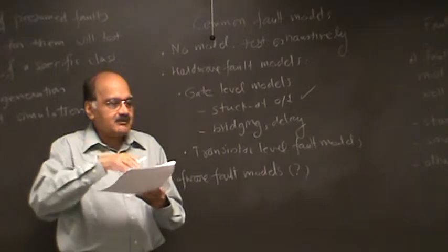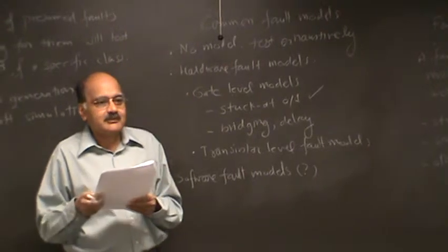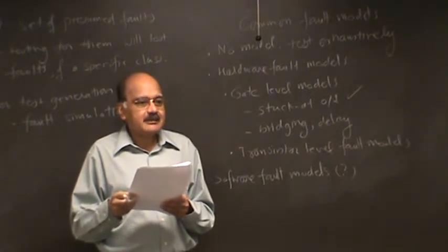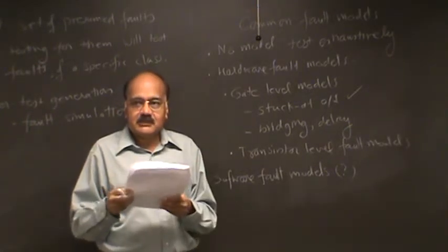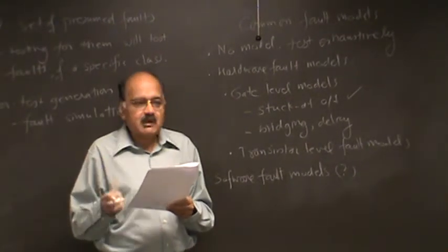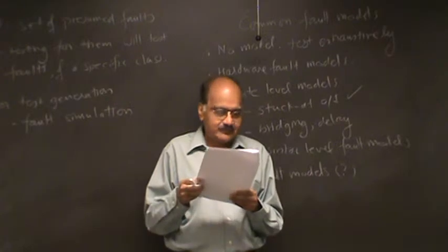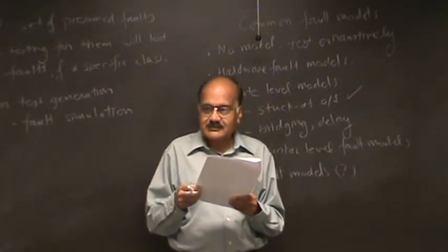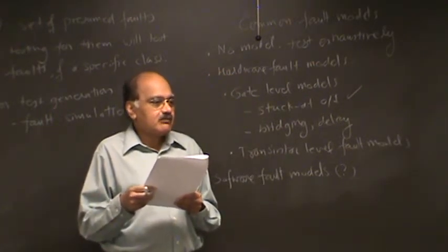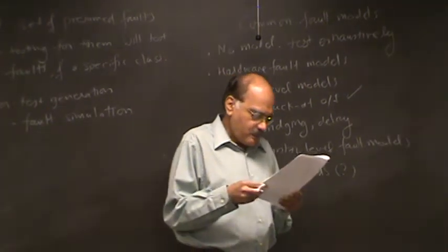And these charged particles are always hitting your memory chip. Even if you encapsulate your memory chip, there would be charged particles coming off from the encapsulating material. So basically, part of nature. And it is possible to design memory chips with a certain amount of robustness relative to charged particles, but you can never control the problem completely. And in fact, the problem has become a little severe recently because the device dimensions have become very small.